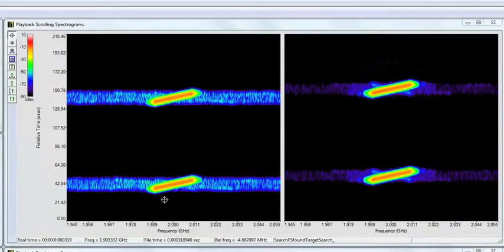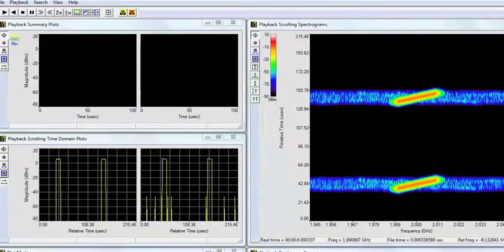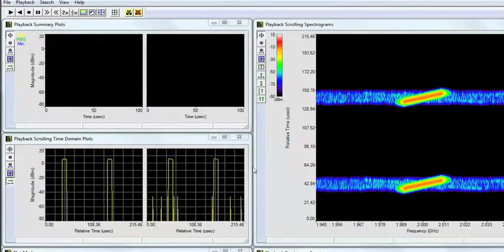And sure enough, what begins to show up is across the 2 channels, there appears to be a time difference between the beginning of a chirp in channel 1 and the beginning of the corresponding chirp in channel 2. This may be, for example, transmission and the reception of the reflected pulse. So there may be some interesting information here to be derived by how long it took for the transmitted pulse to be received in channel 2. We can continue to expand this by looking at just one individual chirp.